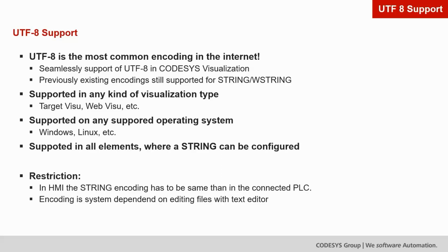Last but not least, all elements. That means any element in the CODESYS visualization which has a string inside, or where a string can be configured, should support the new encoding standard UTF-8. There are 2 restrictions for that. One is the HMI and the connected PLC. Both need to have the same encoding on both PLCs, both applications.